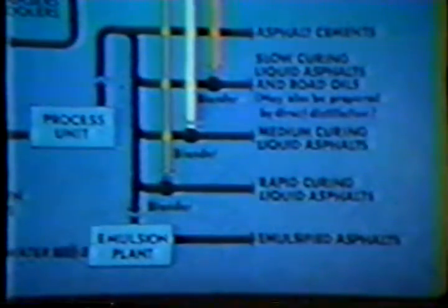That's the pure product. And what we're going to see is that in order to liquefy it for purposes other than hot mix, which is about the only usage we can use pure asphalt cement for, with a couple of exceptions, but in order to use it for many of the procedures you see used in Vermont, you have to liquefy it in a different way than heating so you can use it at ambient temperatures. And the way they do that is by taking asphalt cements and making so-called liquid asphalts. Let me just step ahead a slide or two and we'll come back to this. I think it'll more clearly show you what we're talking about.